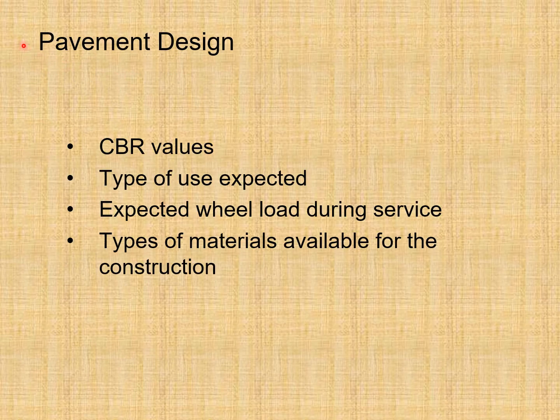So, pavement design using the CBR values. So we need CBR values. Obviously we will have to evaluate the type of use expected, wheel load during service, and types of materials available for the construction. So these are the important aspects that you will have to consider when you are going to design your pavement by using the CBR values.